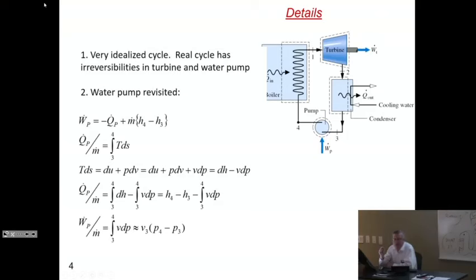It is temperature dependent, but if you even neglect that, it's mostly the same as the enthalpy of the saturated liquid at the same temperature. This cycle is the exception to that statement. In the case of the pump, the pressure difference between 3 and 4 is quite important.